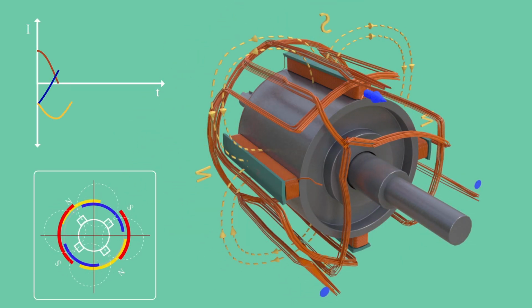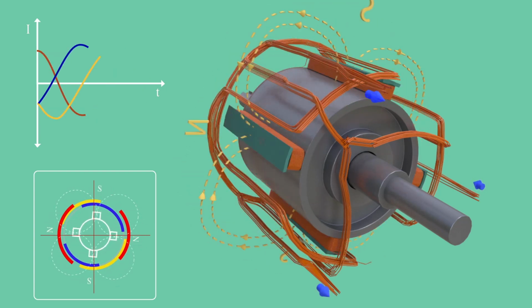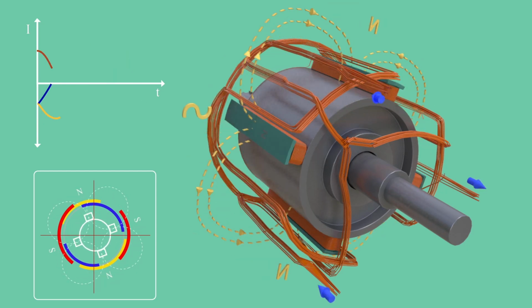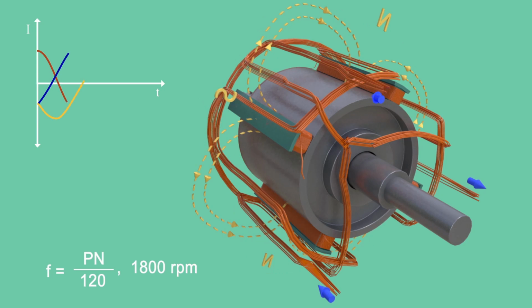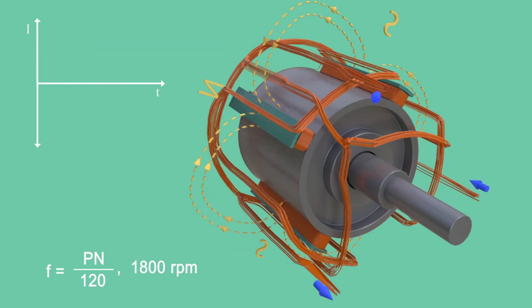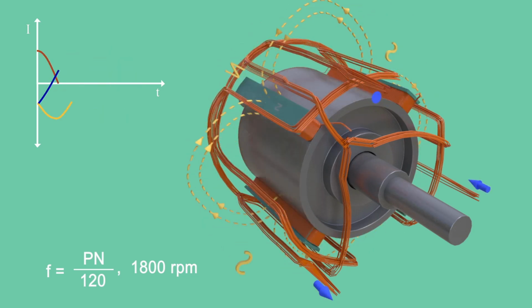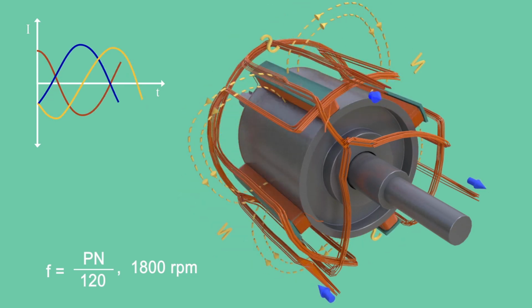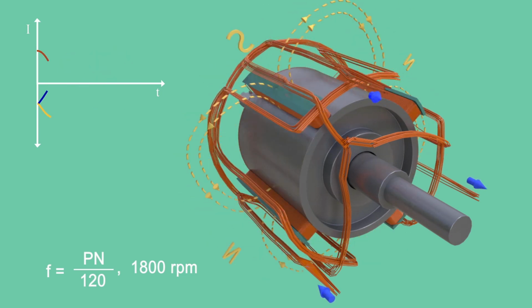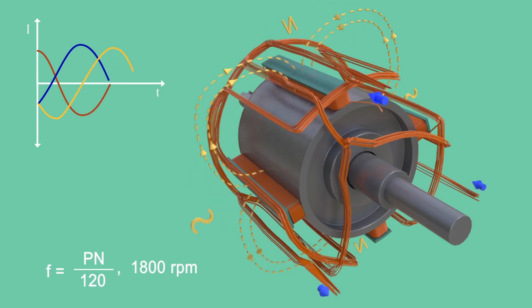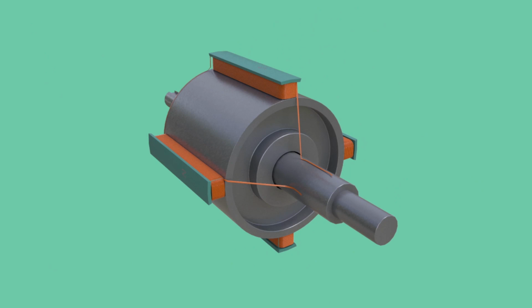It is clear from the equation above that in order to produce 60 Hz electricity a 4-pole rotor should run at a speed of 1800 rpm. Such huge RPM will induce a tremendous centrifugal force on poles of the rotor and it may fail mechanically over time. So salient pole rotors generally have 10 to 40 poles, which demands lower RPM, or salient pole rotors are used when the prime mover rotates at relatively lower speed, 120 to 400 rpm, such as water turbines and IC engines.